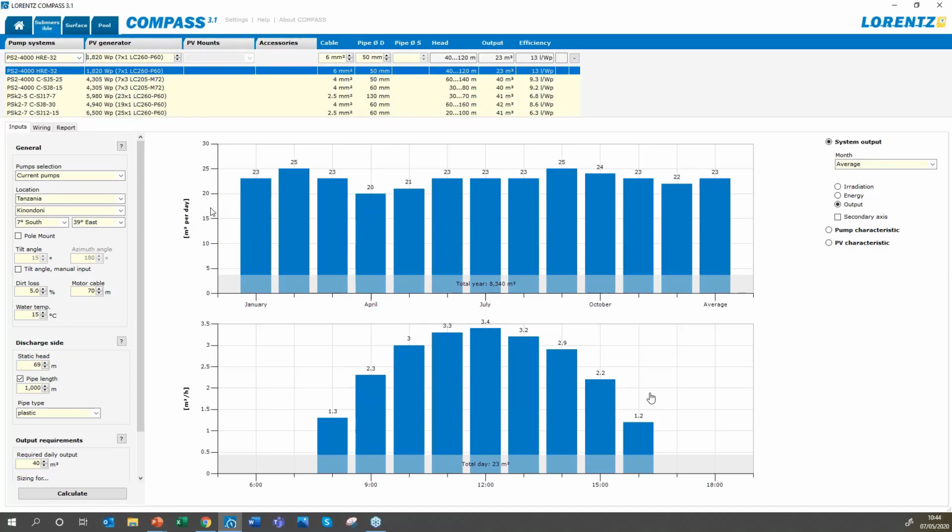Install this now. The price point is obviously more expensive, but not so much more expensive when you consider pulling a pump, installing a new one. It's maybe a few hundred more. Install the pump now, install it with reduced PV, and then when the next village comes online, all we need to do is add some more PV modules. And you could even do this over time.